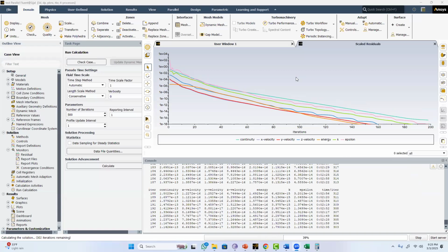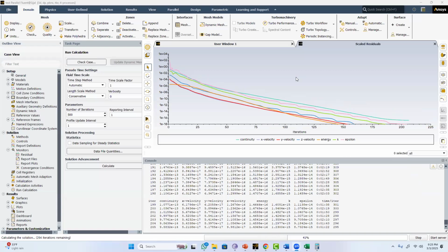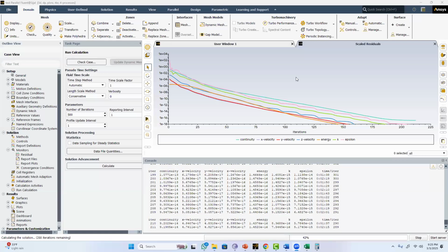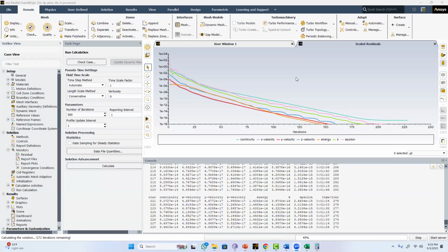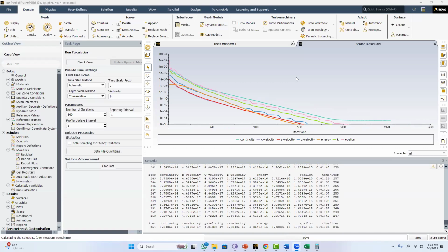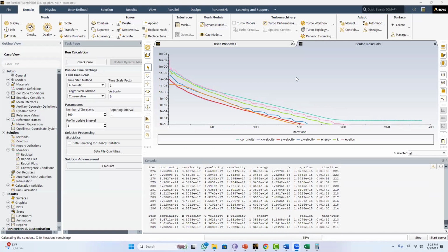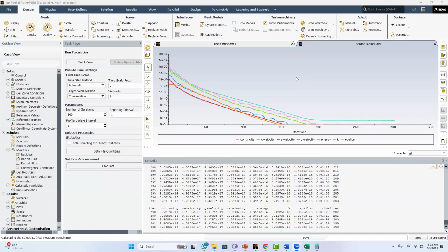that will. But I have done that also. In Sutherland, you know there are two or three coefficients, so we have to provide those. What I do is keep my minimum reference conditions as a constant value, and my viscosity is, let's say, 0.001. I put the temperature and the viscosity corresponding to that condition as the first point. The second and third points will vary with a linear profile, but my bottom value will be what I'm putting right now here in the panel.